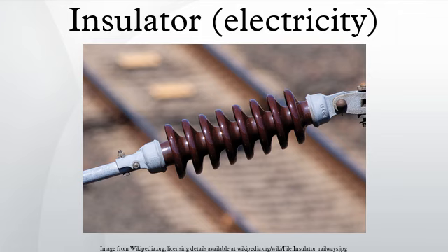Beyond operating voltage of 33 kV, the pin-type insulators become too bulky and hence uneconomical. Suspension insulator. For voltages greater than 33 kV, it is a usual practice to use suspension-type insulators shown in figure.